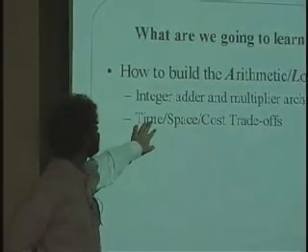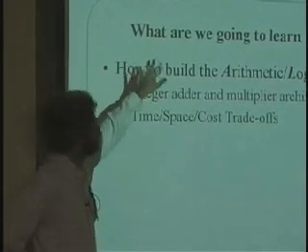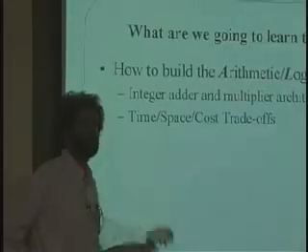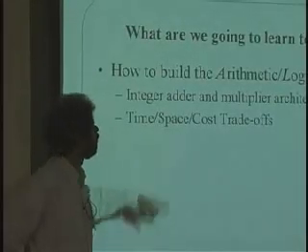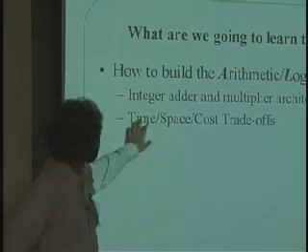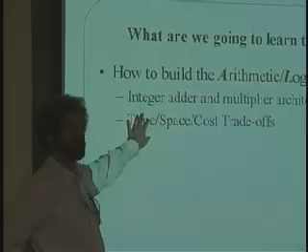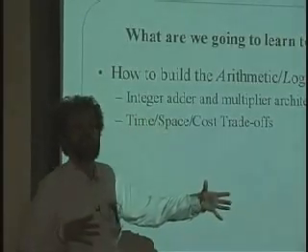But in particular, we're going to talk about how to make an adder that's fast, because if you remember, we wanted the data to percolate through as quickly as possible so that we could clock those registers down at the bottom again without having to wait too long for the data to percolate through a second time. We're going to see that there are trade-offs between how fast a particular architecture is for the ALU and how big it is, how much space it takes up.